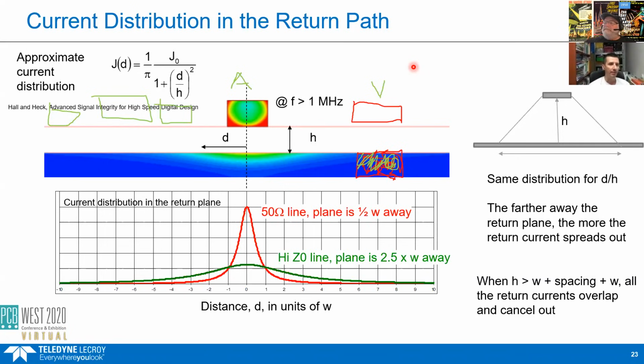What is your opinion if all these tracks are from the same bus? For example, let's say they are all from data bank 0, and they will all be switching at the same time or a very similar time. So can you route them a little bit closer? Because even if there is crosstalk, it doesn't matter because the crosstalk will happen at the time when the bus is not read or written. So what do you think about this?